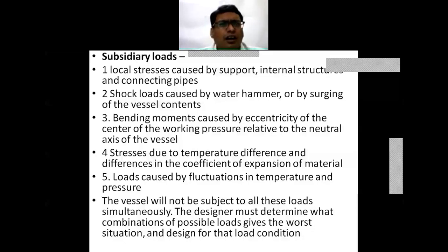We are hammering with something to open the nuts and bolts. That is also a shock load. But this shock load is very small in comparison with water hammering or steam hammering. In steam hammering tremendous pressure develops, and the hammering happens because of pressure differences.